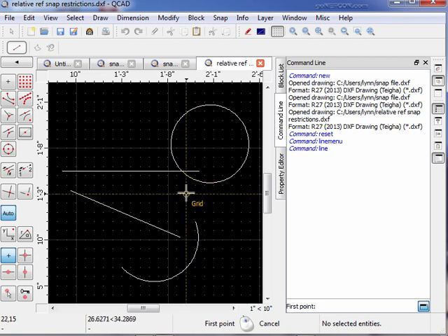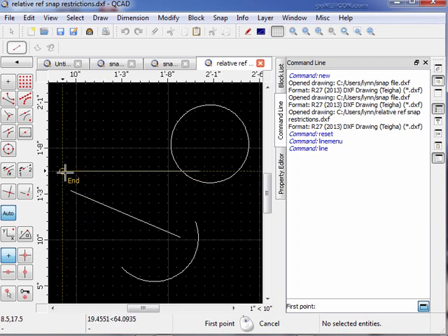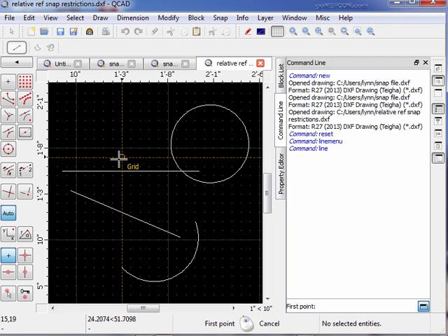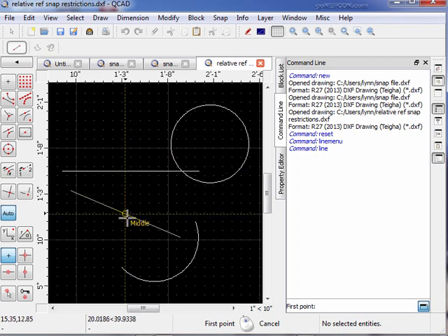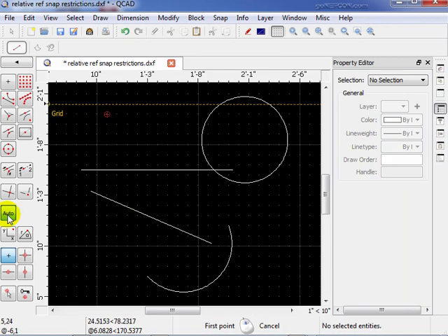This little word that follows around the mouse tells you what you're snapped to. That way, since the auto function does have various things it can snap to, it keeps you alerted as to what you're currently snapped to right this moment. So that's very important. I want you to keep that in mind throughout the rest of this lesson. Auto snap has certain conditions that it will meet.